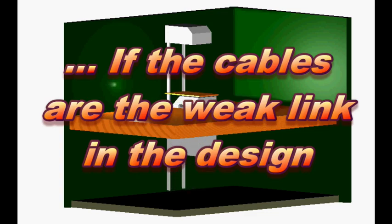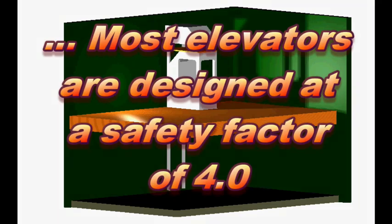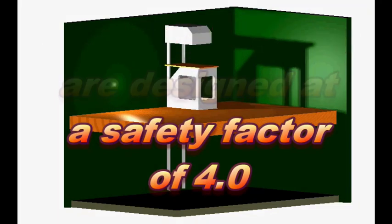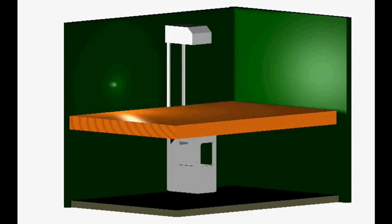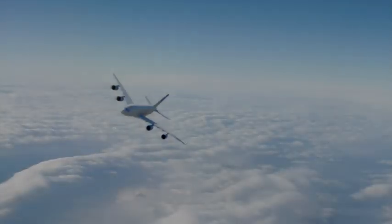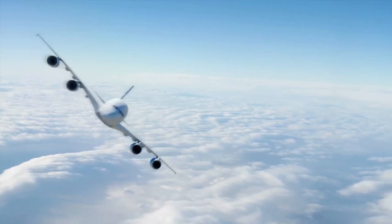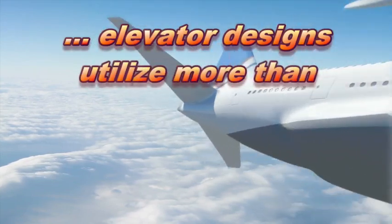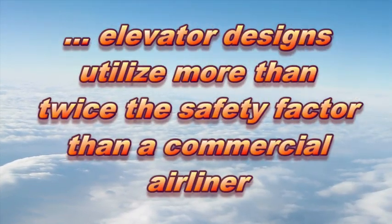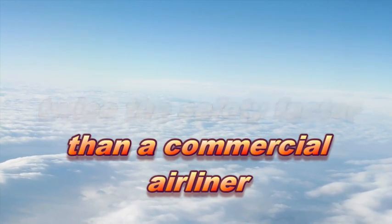For most engineered designs, a safety factor of 4 is considered to be a great number. In the aircraft industry, a factor of safety standard is only 1.5. Think about that when you get on a commercial airliner sometime. The slim factor of safety represents the importance of weight in aviation. It also means that much more time, engineering analysis, and testing has gone into the determination of maximum load and the properties of parts used in the airplane.